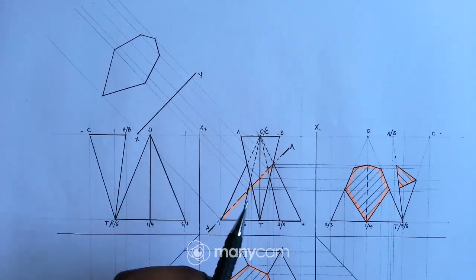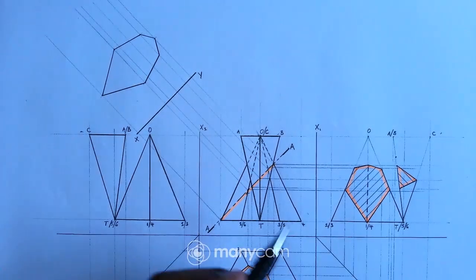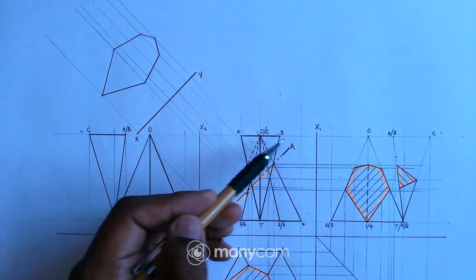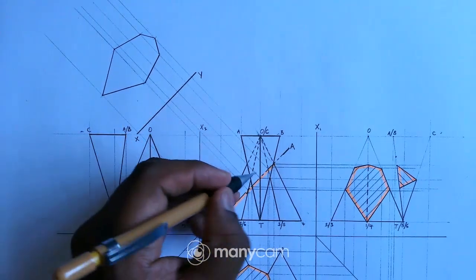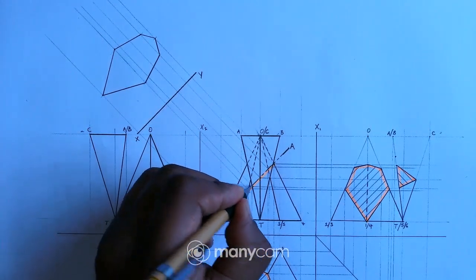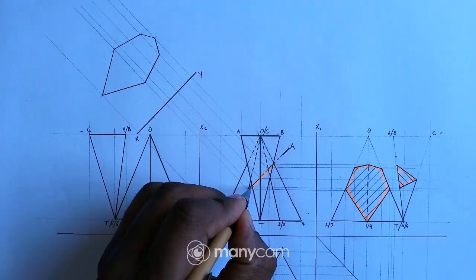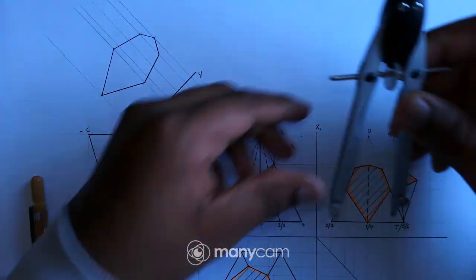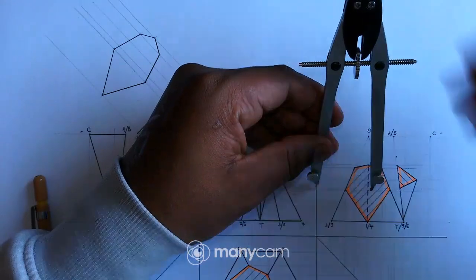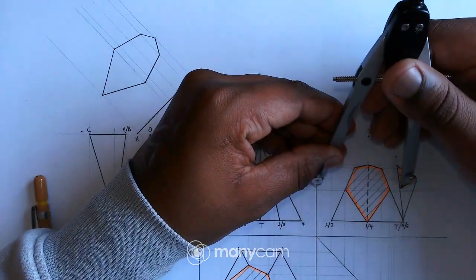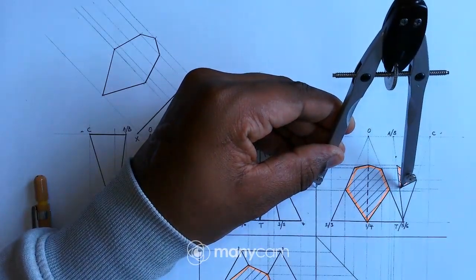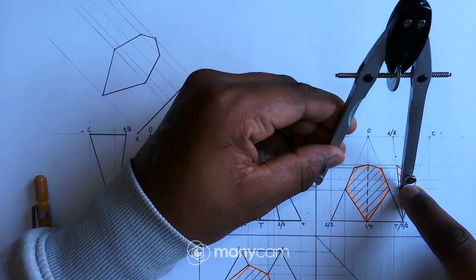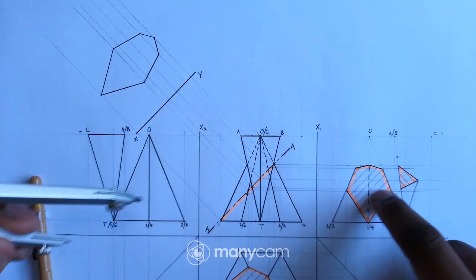Okay, and then now let me try and draw the true shape for the triangular pyramid. So now obviously the first point is right there, so I'll have to use that line. So I'll put my compass on the XY line again, from there to that point there. Cut surface right for the triangular pyramid, it's there.